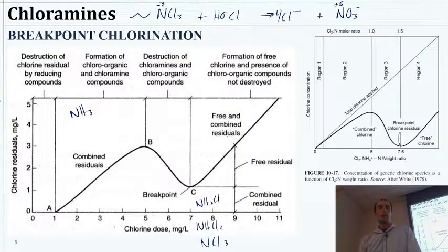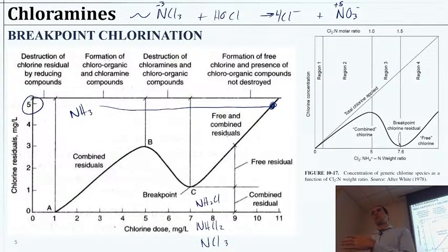So they apply at 5, and this is wastewater, so there's definitely some ammonia there. So they're definitely going through a breakthrough curve. I don't know exactly how much they have to add, but from this graph, if it was the same, they'd be adding 10.5 to 11 milligrams per liter applied to achieve a 5 milligrams per liter residual. And if it was decaying within the 15-minute residence time or whatever they have, then they're going to have to add even more.